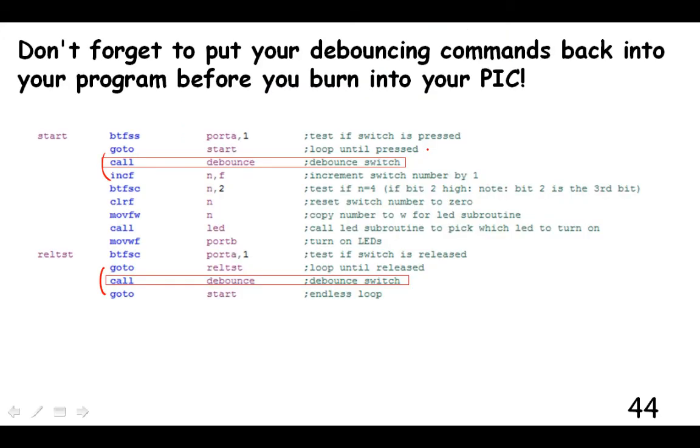Don't forget to put your debounce before you burn. Make sure that you have turned your debouncing routines back on. So remember, we had commented those off when we were marching through the program, so we wouldn't be annoyed by that process. But now you have to turn them back on so that the switch actually operates properly.